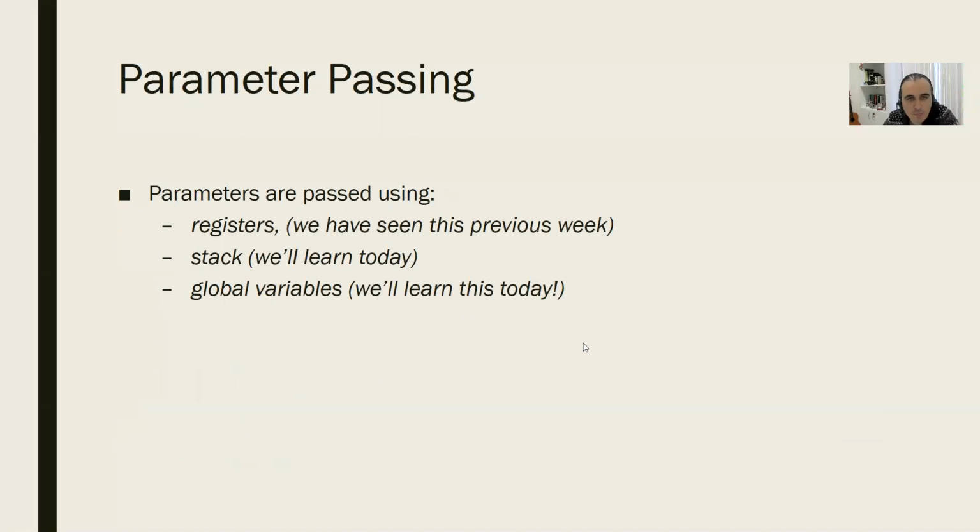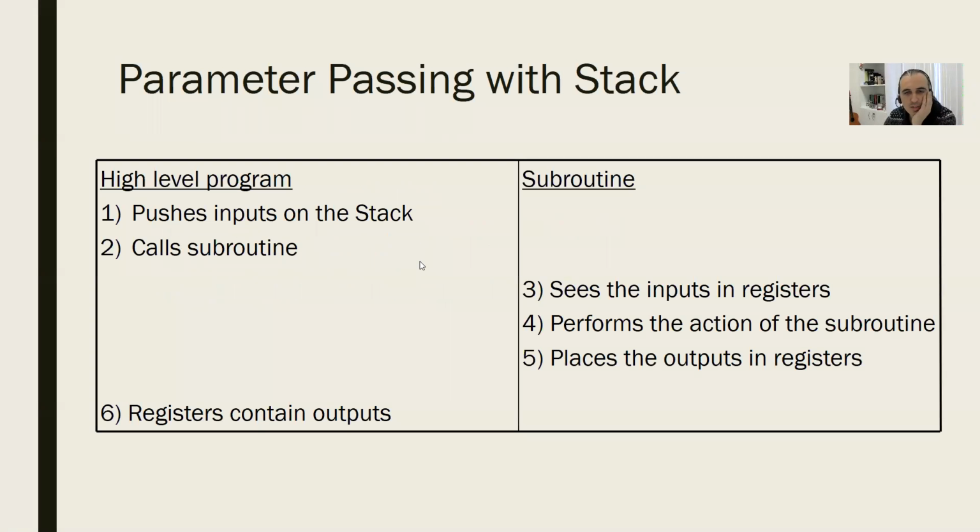Okay, so we start with parameter passing. As I just summarized right now, we could do it in 3 ways: registers, stack, and global variables. We have seen registers. We are going to learn stack today. And global variables, yes, we will learn today because we are going to learn how to use the memory. Okay, so